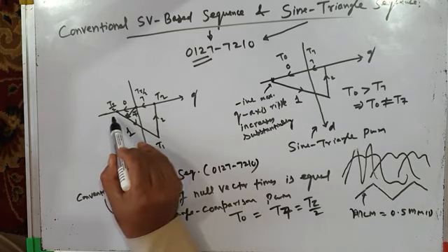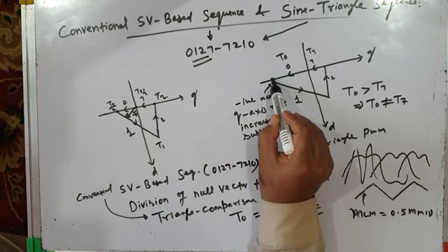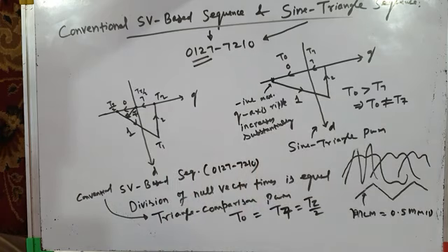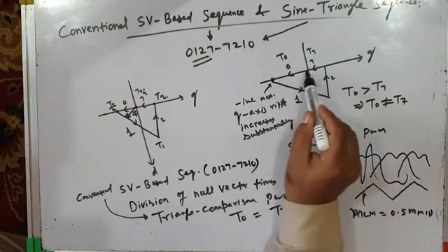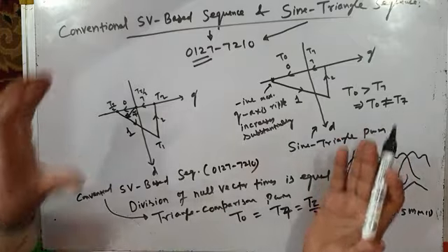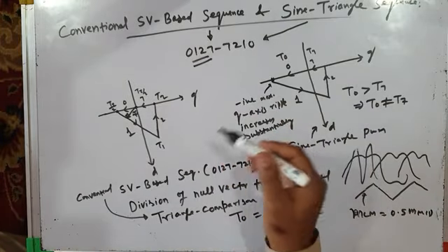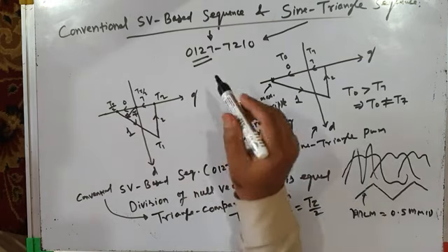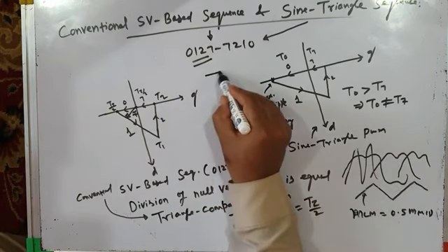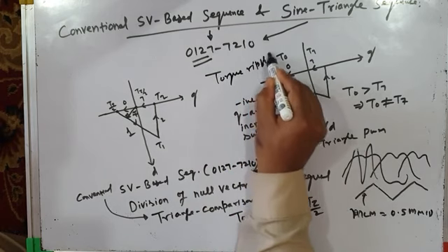Here, this is the negative maximum q-axis ripple. And here, the negative maximum q-axis ripple is much higher than this. And I already told you that this q-axis ripple basically represents the stator flux ripple. So stator flux ripple is more, which means it results in more harmonic torque. So harmonic torque will be higher, so therefore torque ripple will be higher. It will result in large torque ripple.